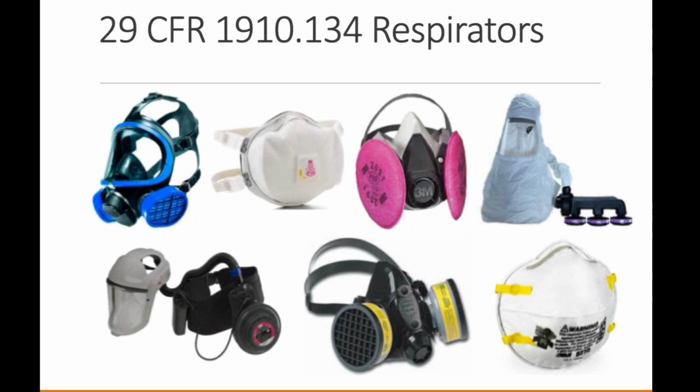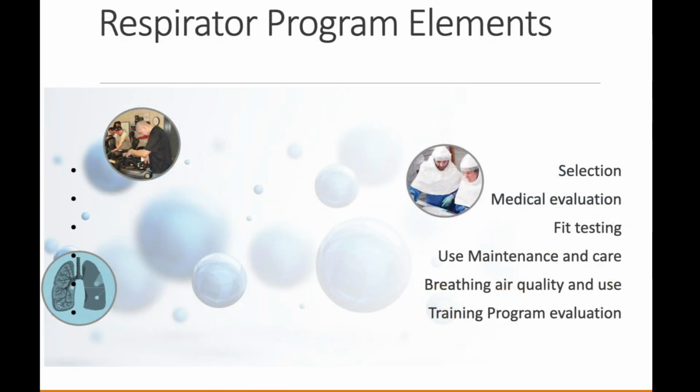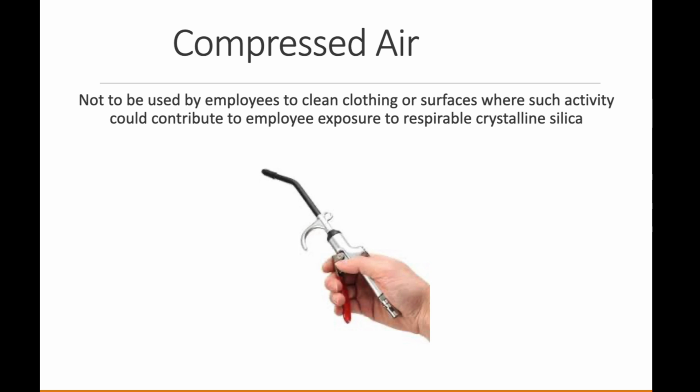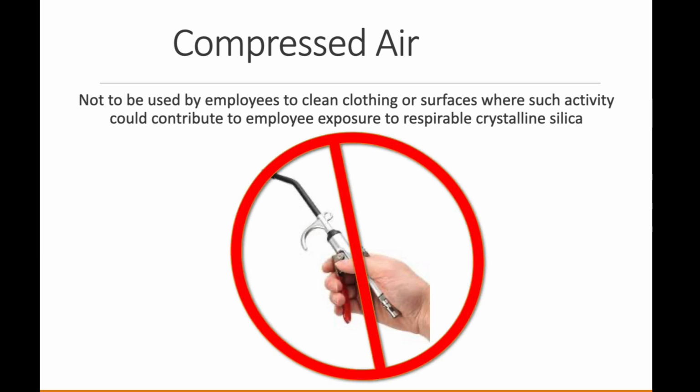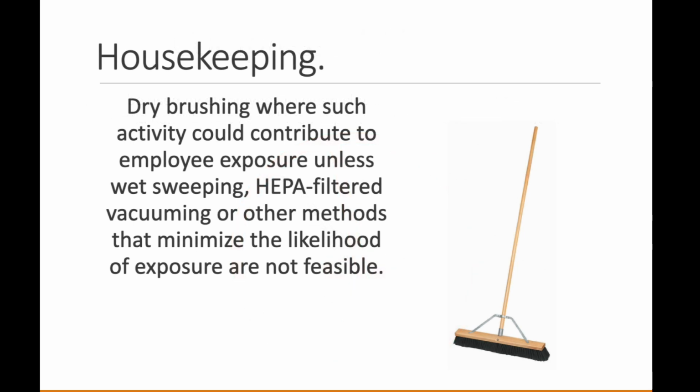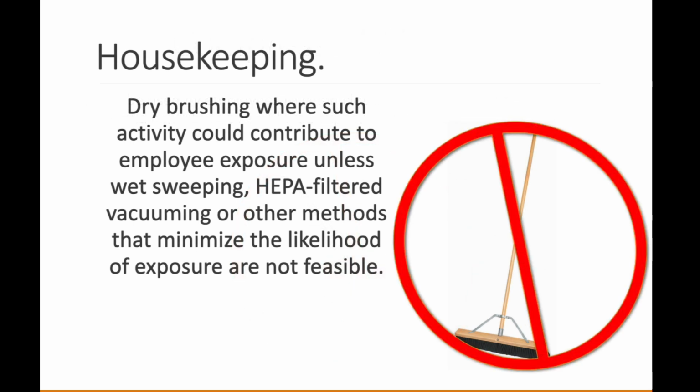If you're going to wear respirators, you have to understand the different kinds of respirators and what kind of protection you get. And if you wear a respirator, you need to be in a respirator program that does everything that is required in 1910.134. You cannot use compressed air to clean work sites up. It makes the situation worse. The rule also says that dry brushing is not allowed, sweeping in other words, because it makes it worse.